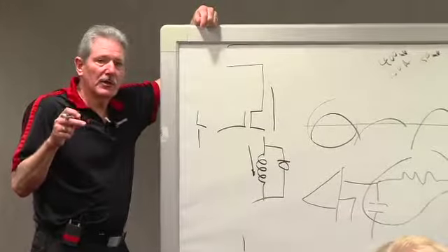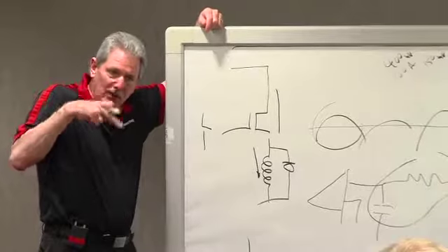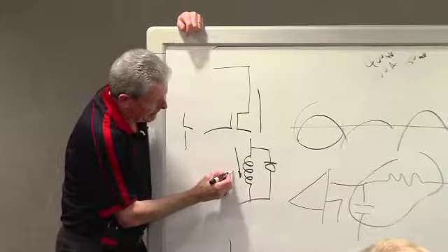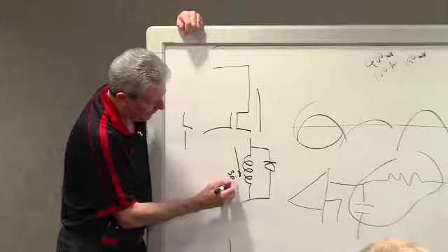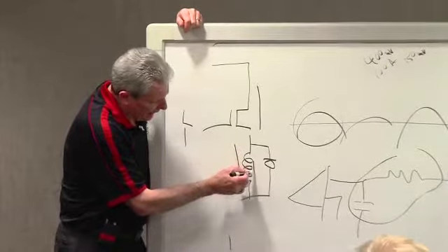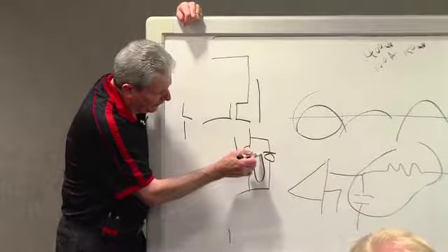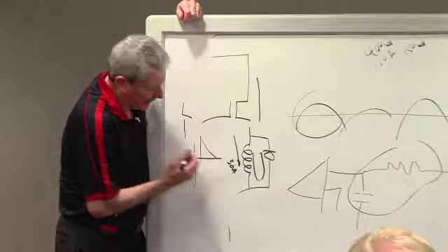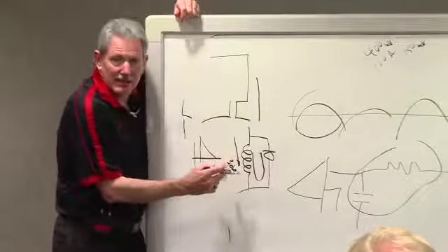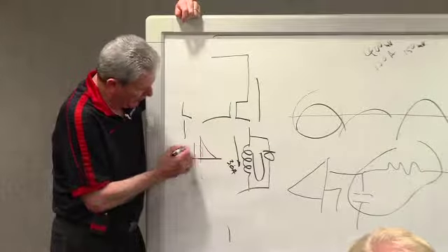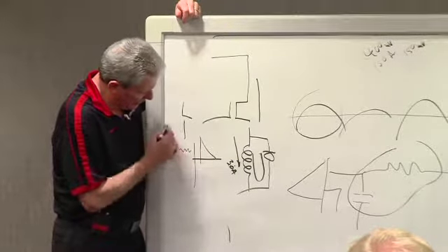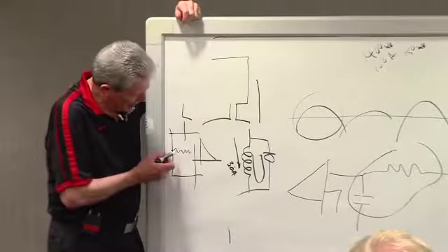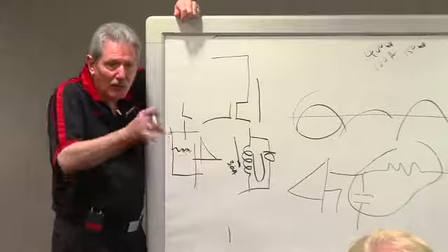Remember what I said, that current in an inductor stays the same at t equals 0, t plus. So this was 3 amps. So it's going to continue, and it's going to flow, and it will go through this exponential decay. Well, the time that it does this is very short. So really what you've got looks like a direct current because it's just got a small amount of ripple in it between this time.